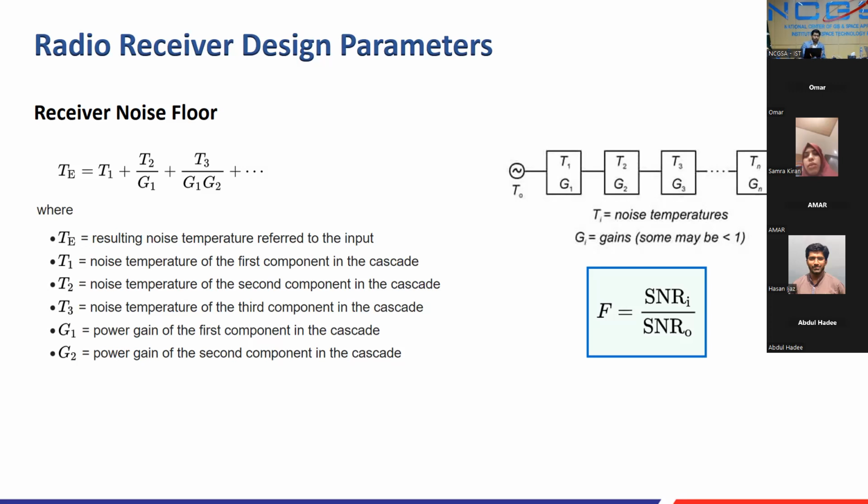In practice, in all data sheets for amplifiers, LNAs, there is a figure of merit of noise figure. So in terms of making a sensitive receiver, you need to give a lot of thought to noise figure. I can share a practical example before going into the detail of this.